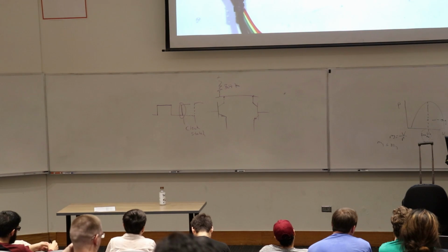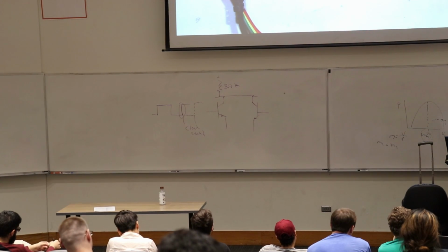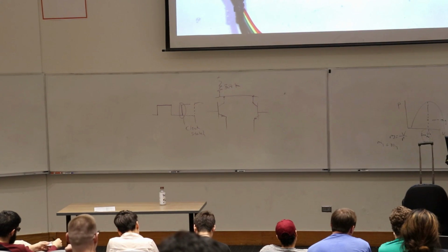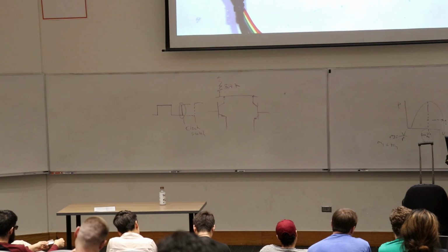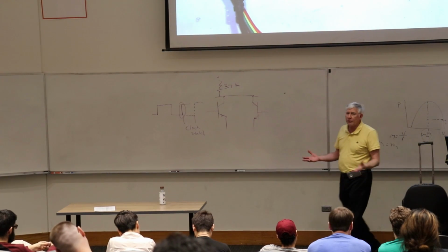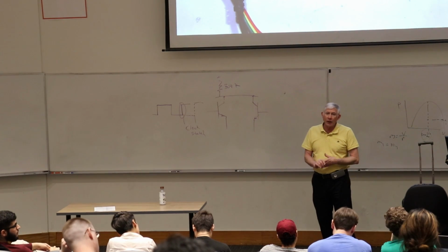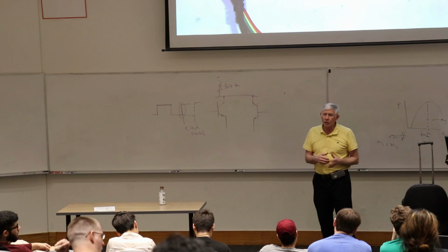And then we have the ability to do address masking. That's for a slave. So if you set it up for a slave, you can have your chip respond to a range of addresses instead of just a single address. Sometimes as a master you may want a whole bunch of slaves to respond to a single command, and other times you want to address each slave individually.